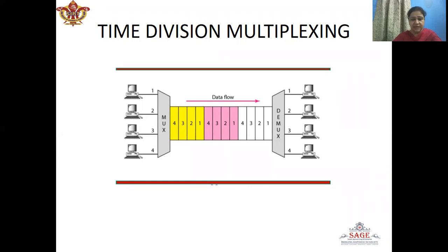And so the interval Ts, which was initially used to accommodate only one signal, is now used to accommodate four signals. So here, four samples from four sources are transmitted simultaneously by occupying the sampling interval Ts. So this is called time division multiplexing. Now these samples will be received by the receiver side, and the samples of all the four sources will be recovered by their destinations respectively.